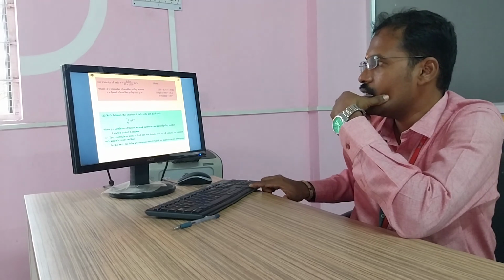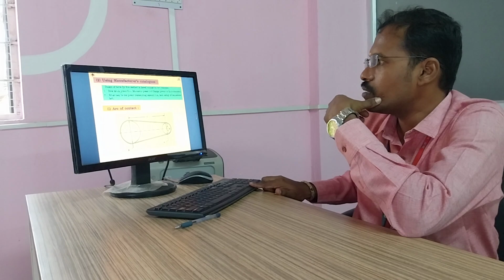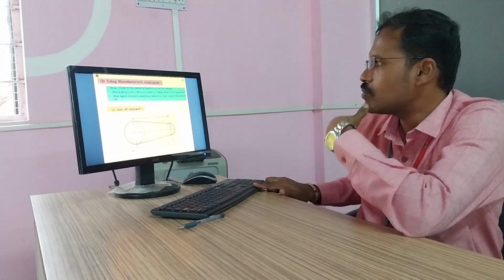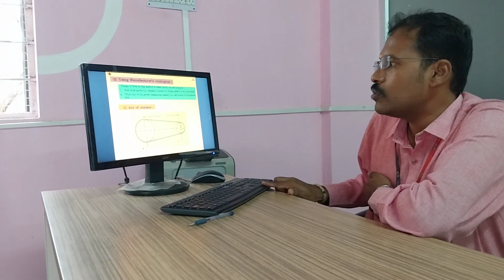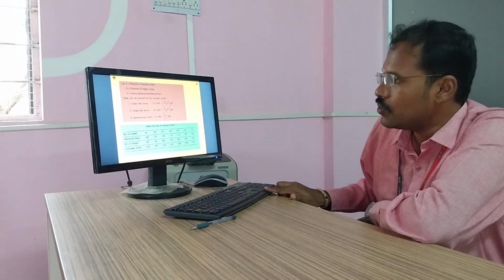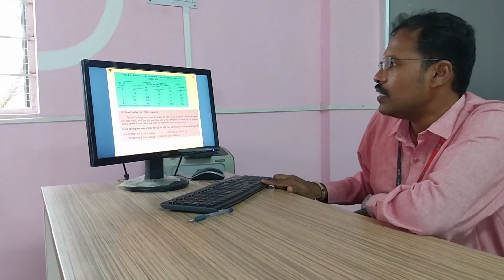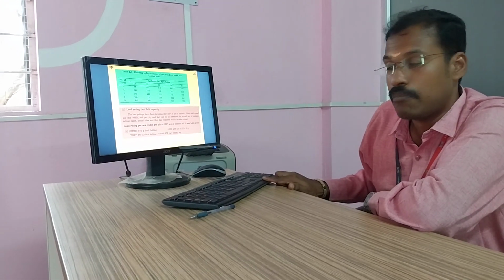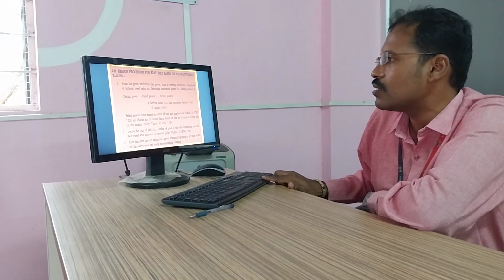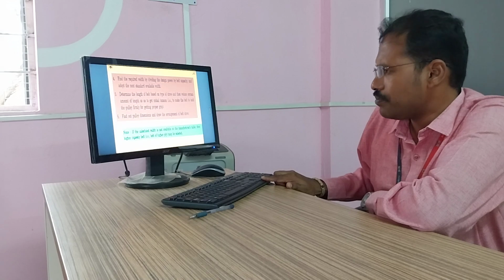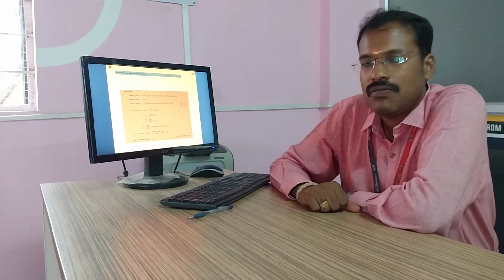What are the steps to design the cross belt drive system? First, you should calculate the design power. Next, the power transmitting capacity of the belt should be calculated. Next, we should calculate the arc of contact factor for the specific belt drive system. Next, we should design the belt plies based upon the velocity, load rating, and selection of belt drives. These are all the primary steps to design the flat belt drive system.